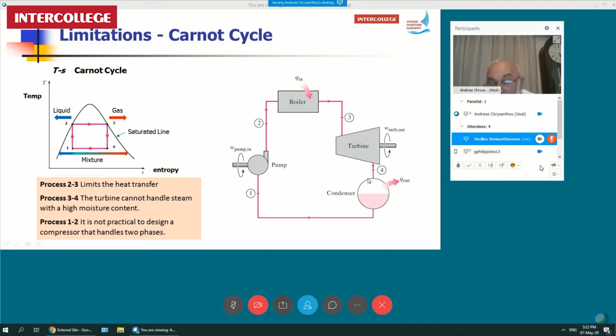And this is the area where you made your question previously, that when you move from a higher temperature to a lower temperature, there's always useful work done. Now, during the expansion, the turbine turns the shaft, which in turn turns the generator to produce electricity. This is the useful part of the station. Now, going back here to the condenser, this part here on the cycle, we condense that back to liquid form for the pump to pump it again back to the boiler.